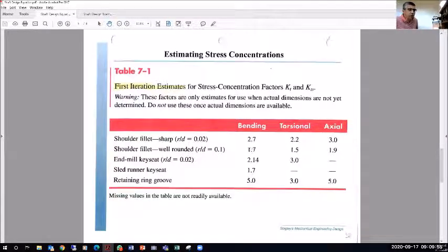And please note that these stress concentration factors have a significant effect because in some cases they are more than doubling the stress. That's why I said for homework 3, you ought to check for A and C. Even though we know for sure that the bending axial stress is higher at point C, but should the KT be higher at point A, then maybe the location at A is going to become more critical or lead to the minimum design factor. But I think this is something that you can easily look at by knowing the dimensions as given in homework 3.